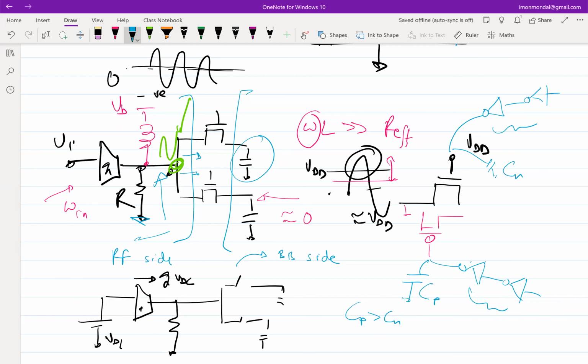Make sense? So power consumption wise, this is not an ideal scenario. So okay, let's say I am okay with the power consumption. There is another problem. You will never be able to ensure that when this guy turns on, at the same time instant, the PMOS also turns on, because they have different threshold voltages. You can probably ensure the rise and fall times align, but you are never going to ensure that the threshold voltage is exactly at the midpoint or wherever you want it to be.